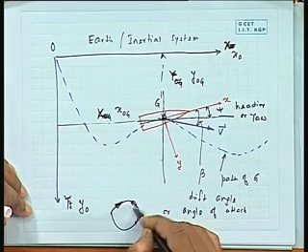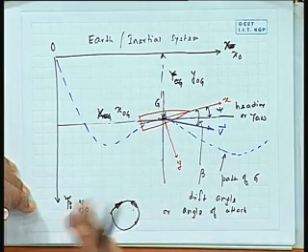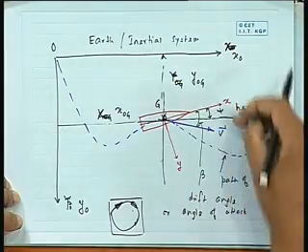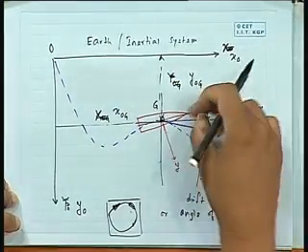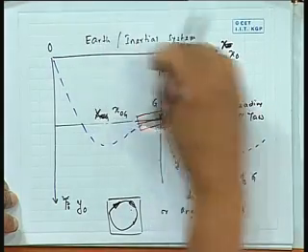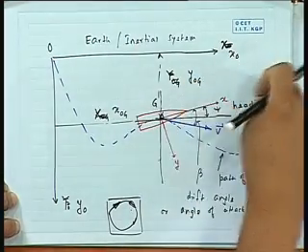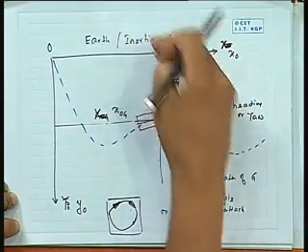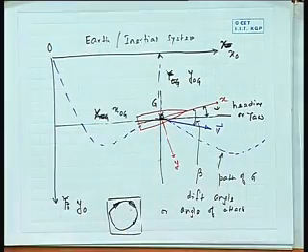You have to have an angle of attack. Okay. Because without angle of attack you cannot have the force on that. So, I will come to that later on. That is an interesting part, unlike hull or any other things that you will find, because here there is no external force, the only force is fluid forces acting, that cannot act unless there is an angle of attack. Flow must come with an angle, because if the flow came along the x axis, there is no force on this side, that would be like a ship moving on a straight line.